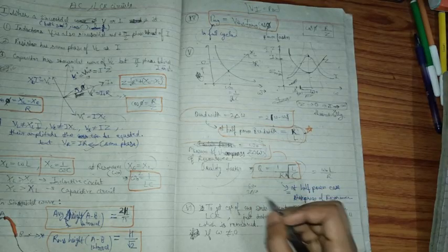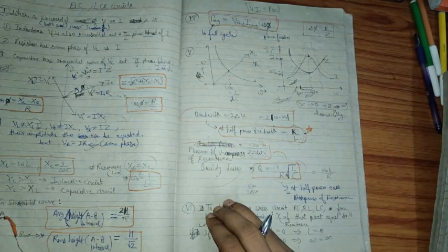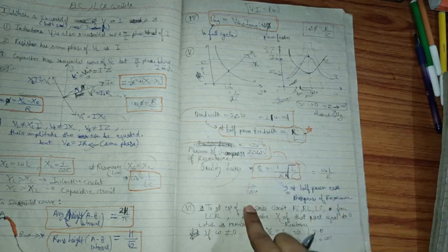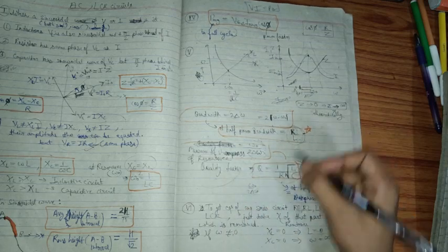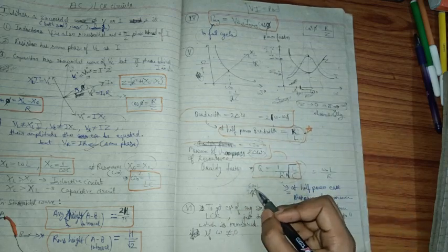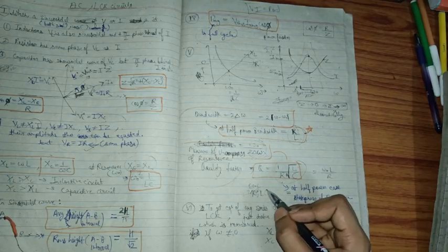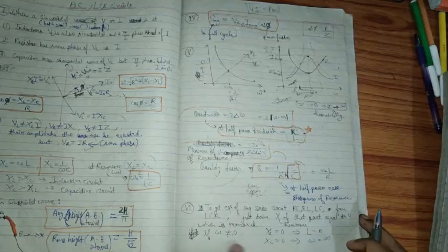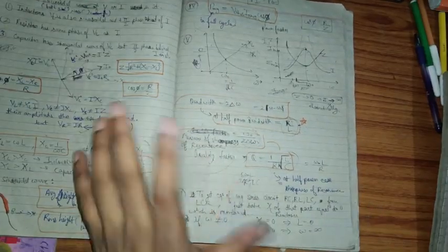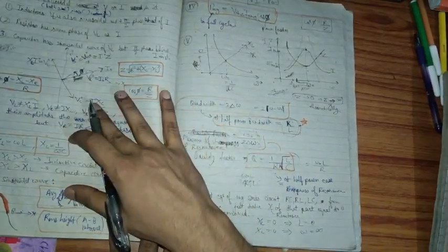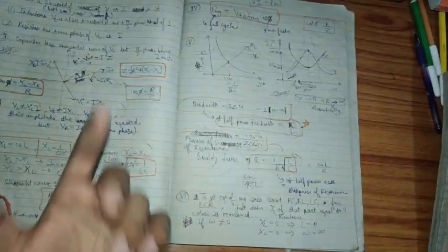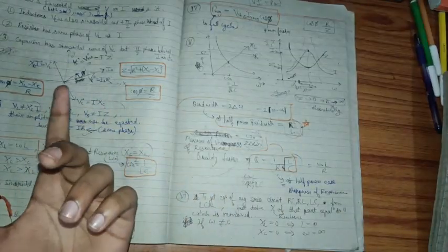Now I have only told you the RLC circuit. If we have to use the RL circuit, RC circuit or LC circuit with the AC supply, then we have to get the equations for such cases by making that resistance or reactance equal to 0, which eliminates it from the system.